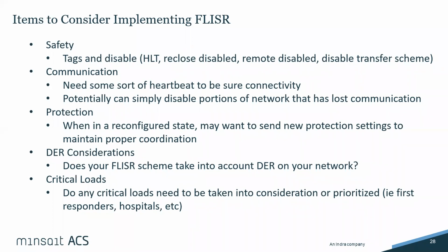Protection, when you're in a reconfigured state, you may want to send new protection settings to maintain proper coordination. What will your FLISR system do for that? Will you maybe rely on the devices being smart enough to know that they've been reconfigured to change their protection settings? Some certain things to consider.